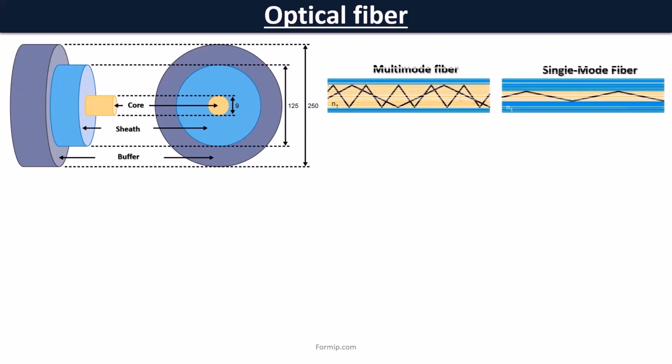Now let's look at the two types of fibers, single mode and multi-mode. The difference between the two is the ability of the fiber to send light over long distances at high speeds. In general, multi-mode fiber is used for shorter distances with much lower speeds than single mode. For communication over long distances, we'll see single mode. In the image that represents the two modes, we see that the main difference is the size of the nucleus. Single mode fiber costs more than multi-mode.